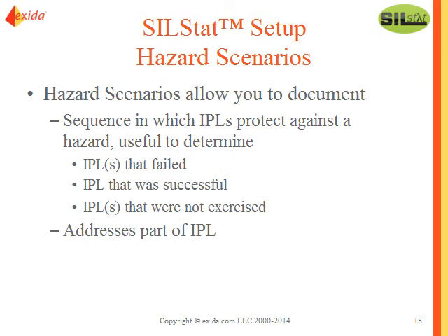The hazard scenarios will allow you to document when there is a demand from the process. When you set up a hazard scenario, you indicate the sequence in which the different IPLs are expected to act when a certain hazard occurs. For example, for a high pressure event, you expect the pressure relief valve to act after the safety instrumented function has failed. You expect the safety instrumented function to act after an operator would have failed, and you expect the operator action after a control function, for example.